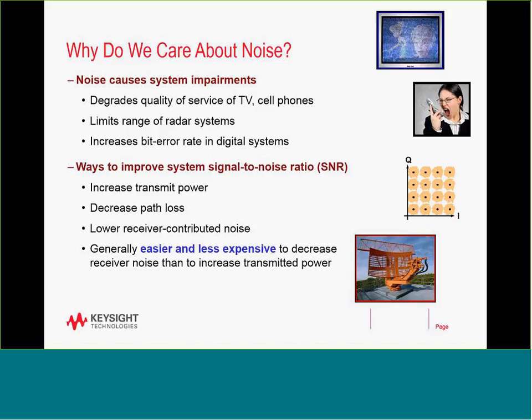So why do we care about noise figure? Well, noise causes system impairment, so it degrades voice and the quality of signal transmission. It limits radar systems. It increases error rates in digital systems, increasing ISI, intersymbol interference, and so on. So it's basically a direct effect on signal to noise.